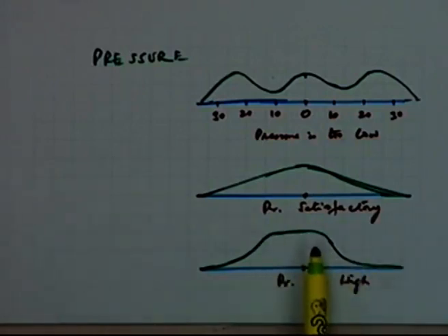This plateau is formed because when the breakup of the stream or the jet is too excessive, the size of the particles will be very small, and they have a tendency to settle very near to the sprinkler head position, which is somewhere here. So most of the water settles in the near vicinity, and you get this type of water distribution.